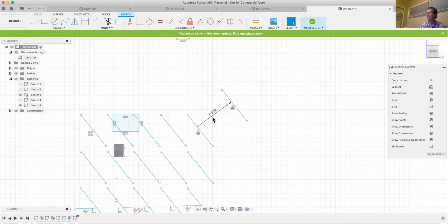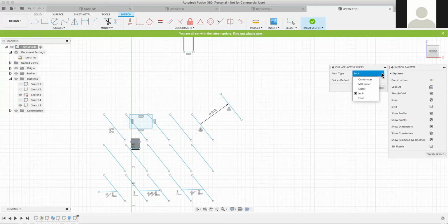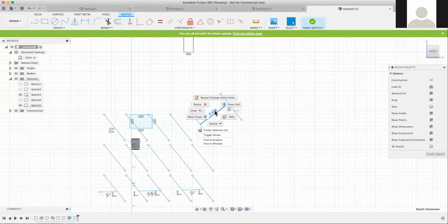They'll show in decimal. Let me see. You can try right-clicking on it, and it might allow you to change a specific instance to show inches. Well, does this give alternate dimensions if your default is millimeter and you want to have alternate dimensions of decimal inches in your drawing?